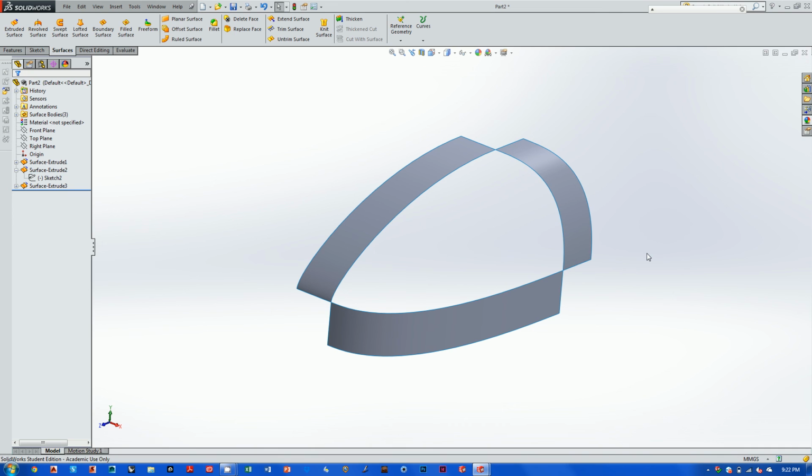And then finally, we're going to run a surface fill that's going to use these 3 boundary edges of this situation to fill. And then we're going to use the profile curves differently than we did in class. In the future, we're going to use these profile curves as something called constraint curves, which is something I didn't even touch on in class. Okay? All right, so get yourself to this point, and then once you are, move on to the next video.